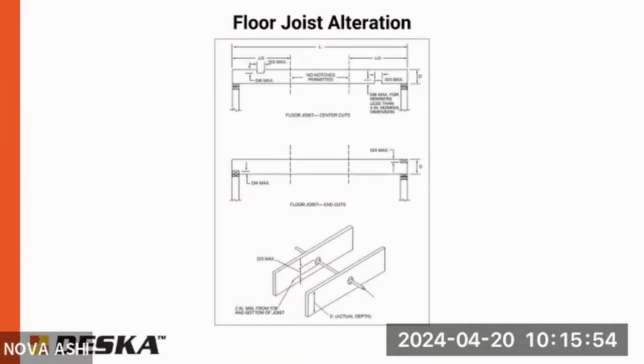The building code actually tells you where and how you can alter a joist, and it depends on where as well. So just something to be aware of. If you're in the outside 2/3, you're able to notch it, but there are limits. If you're in the middle third, you can bore holes in it at about mid-height, but you cannot notch the top or bottom of the joist. Those are the areas that are in the most tension or compression. The areas closer to the bearings at the ends are just in shear, so it's a little more forgiving. This is straight out of the building code.